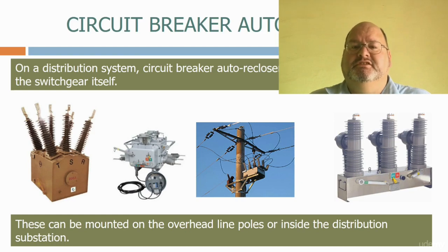Auto-reclosure provides a solution to this problem by allowing the circuit breakers to reclose after the fault to see if it's been cleared. If it has, the system is restored at no cost to the network, and the customers have had minimal disruption. If a fault is still present after reclosure, the system locks out and an engineer is dispatched to resolve the issue.